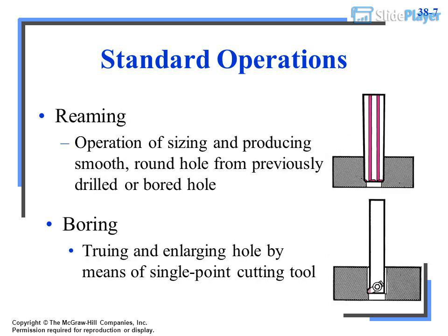Standard operations: reaming, boring. Reaming is the operation of sizing and producing a smooth, round hole from a previously drilled or bored hole. Boring is truing and enlarging a hole by means of a single-point cutting tool.